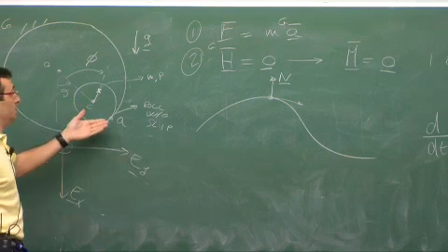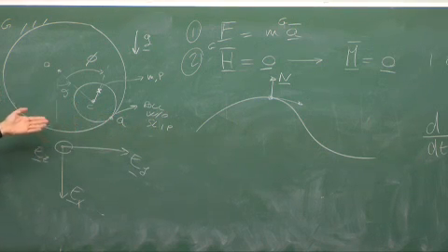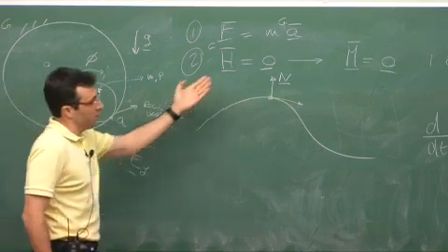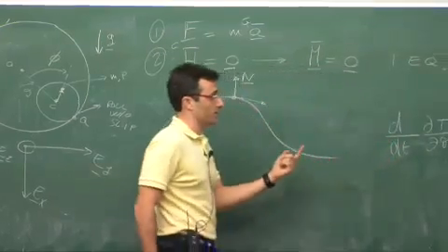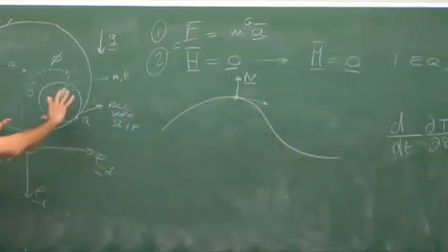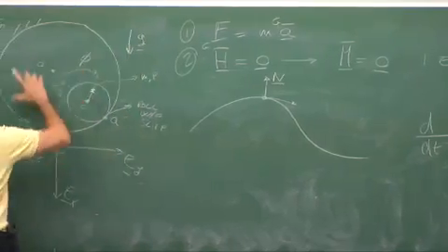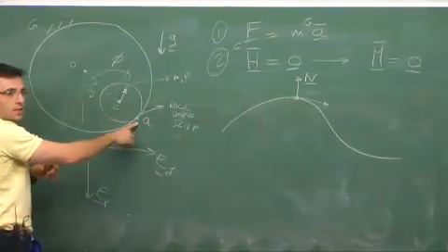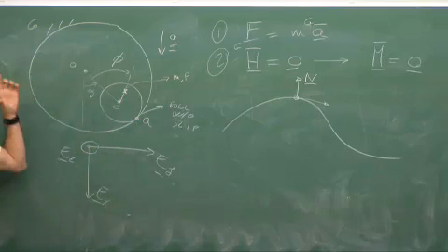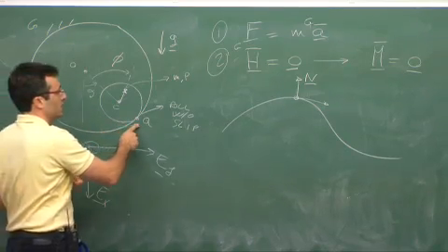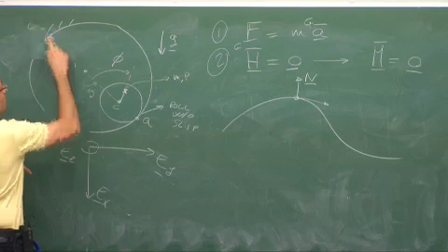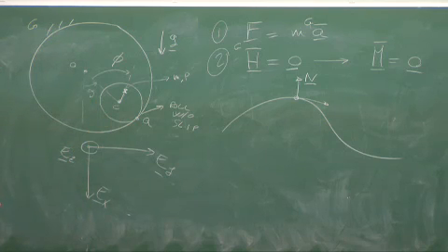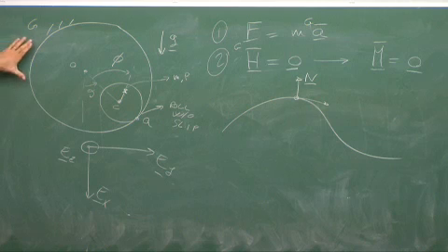Actually, I think we said last time that rolling without slip is a kinematic constraint, but there is a force that allows you to have that constraint, and that's the friction, the static friction force. In other words, say that this guy is able to move in time, but I'm still telling you that there is roll without slip, you still need that force to give you roll without slip. So it is a constraint force that allows you to say that the velocity of this point Q, doesn't matter if it's on the ground or on the disk, is the same. In this case, the ground is not going anywhere, so it's 0, but this could actually move around.